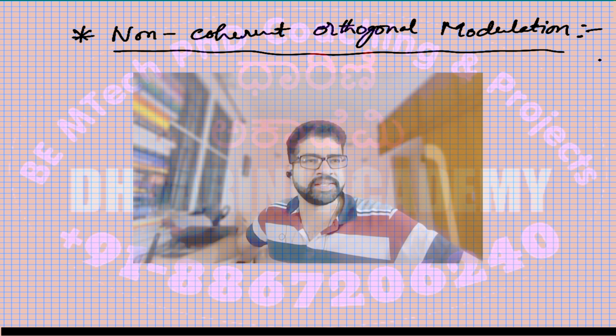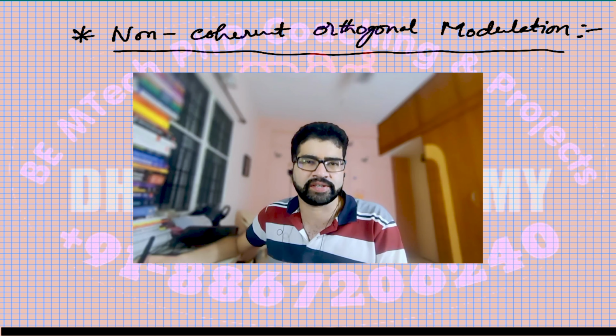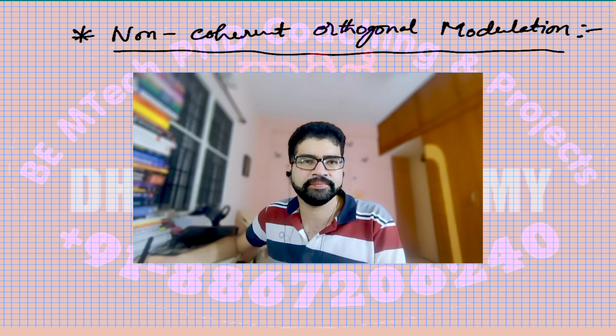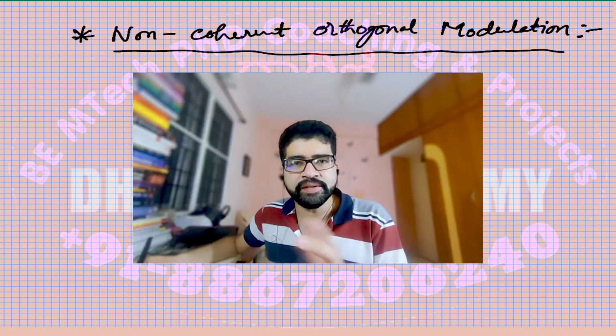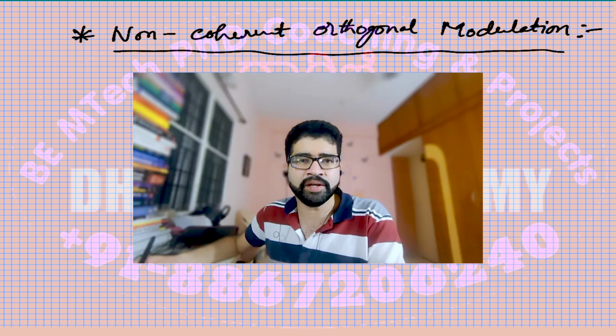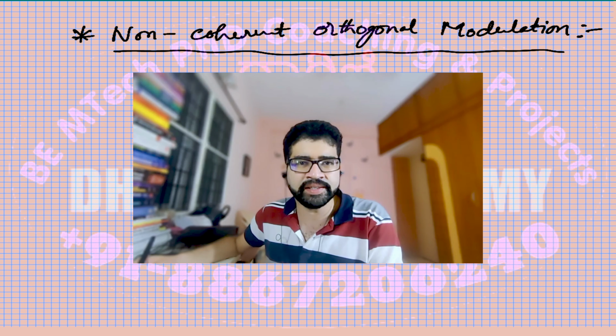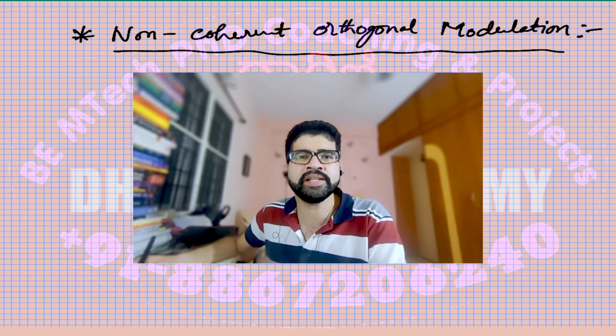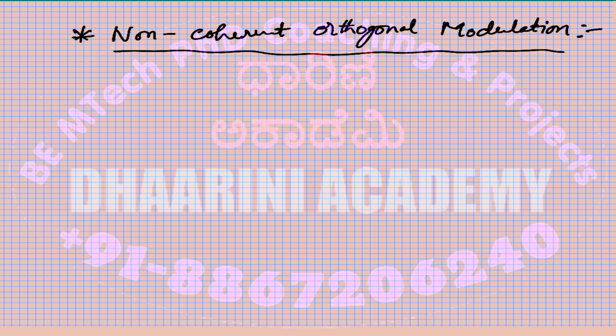Now, when I say non-coherent orthogonal modulation, there will be two or more symbols to be transmitted on mutually perpendicular axes, like phi 1, phi 2, phi 3. We have already seen one such application in the form of FSK. But that was a specific case. Now we will see all such modulation techniques under one heading, and we will consider the equations in the general format, not a specific case like FSK.